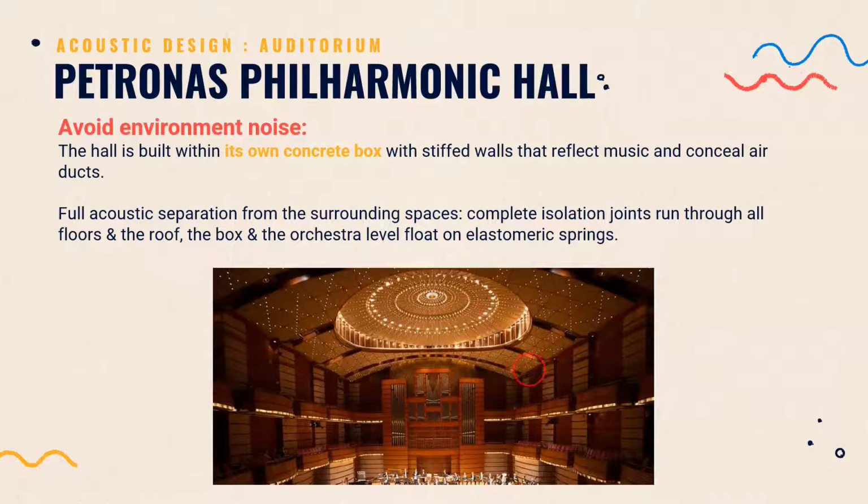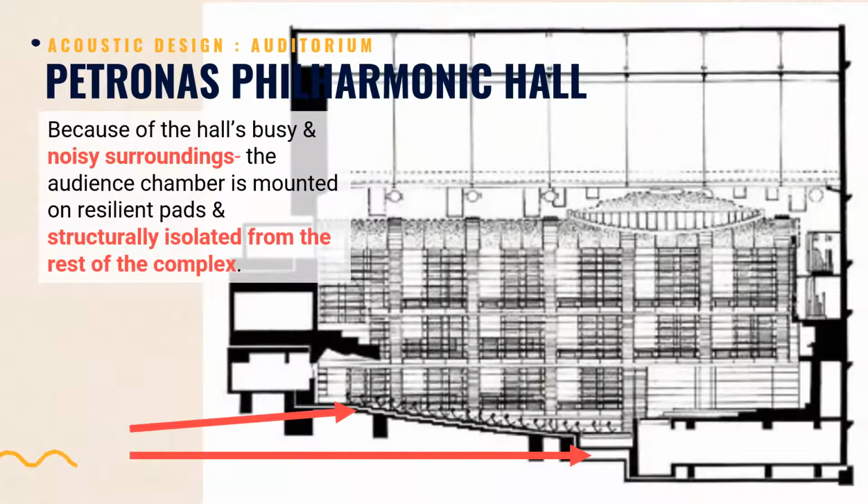So let's see the section in the next slide. Notice the gap here, see? Because of the hall's busy and noisy surroundings, the audience chamber is mounted on resilient pads and structurally isolated from the rest of the complex. So remember, KLCC even has LRT below it, and it's surrounded by big buildings and a lot of busy roads.